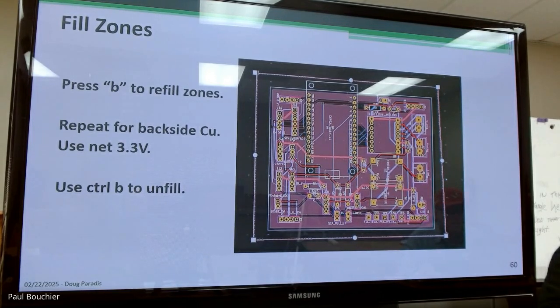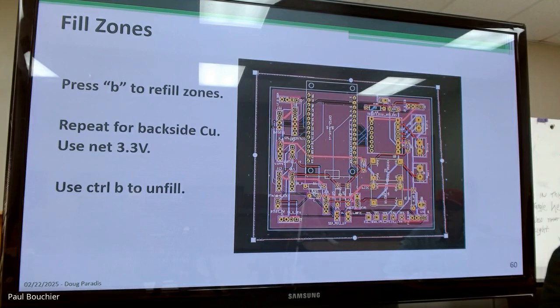Ray had a question. How do you add mounting holes? You mean inside of the border? Yeah, inside the borders? Well, okay, Ray, yes. That's why I said I like to use Inkscape, but I can't use that now. But you can use the circle tool. You see there's a little circle tool. You can do that to drop holes into the border. Okay. What layer would you select?